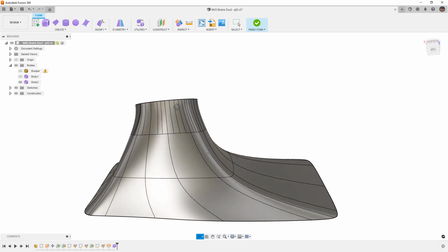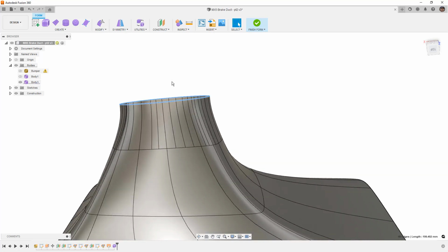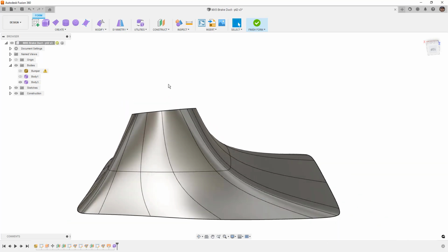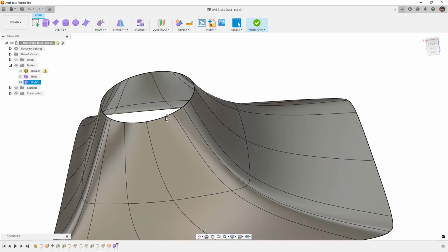So because the back end was matched to an extruded cylinder and it already has the tolerance on it and it has all these divisions, what I'm going to do is double click this back edge and hit delete to get rid of it. Then I want to create just basically a wide single opening here. I'm going to do that by double clicking on this edge. You will notice that when we look at this edge, because it was broken up with those T-points, that it ends up having a lot of divisions.